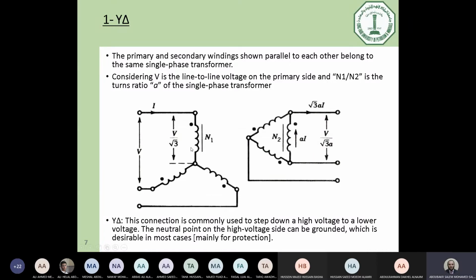So we have three identical coils here. How to construct a Y connection? Simply, you have to connect like that. If you start here with the dot, then coil, the end here should be the same, with the dot, for the three phases. Otherwise, it will make a problem in the magnetic transfer. So this is now the star connection.